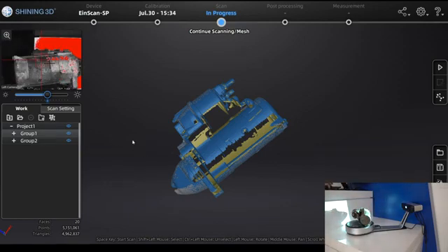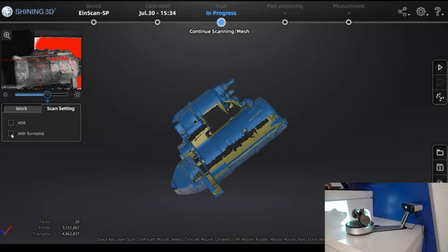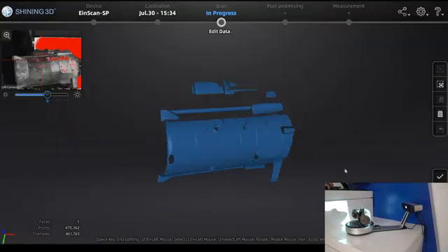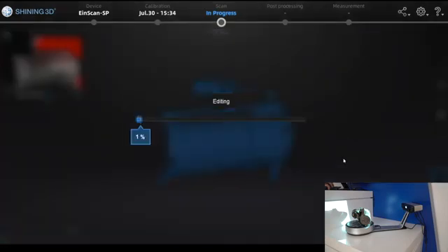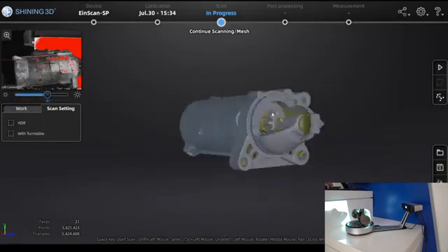And then what you can do on the scan settings, now for example we just want a single shot, so we don't want to use the turntable. You can just turn it off, and here with this position, also on the left top, you see what the scanner sees. The scanner will now just do one shot of this position. And then as before, the scanner will try to calculate to align these different scans if there is enough overlap, and in this case it aligned automatically again.